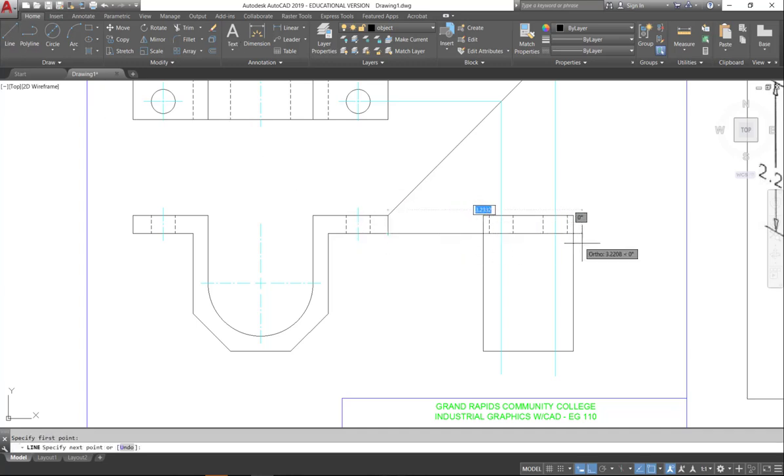That's going to project over. I've got this edge that's going to project over. And I've got to cheat a little bit here because I need a center line from here. So let's trim this first and get rid of the extension lines. Now I don't need those.